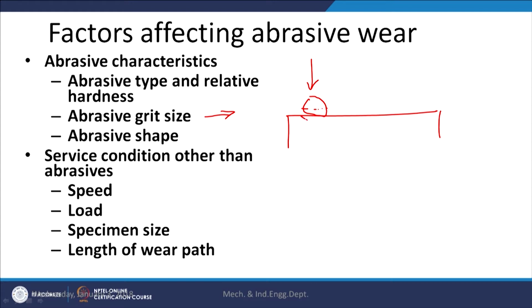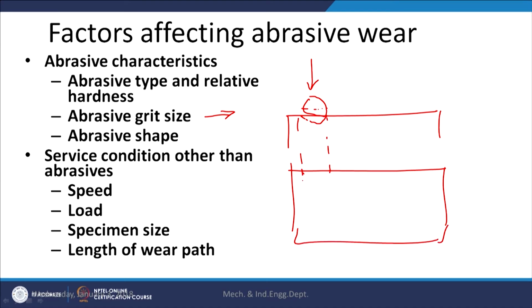So, the maximum indentation caused by the abrasive particle will be smaller, and under abrasive wear conditions it will form a scratch of the same size along the length of the workpiece as per the abrasion, until the scratching is stopped by the presence of hard particles.